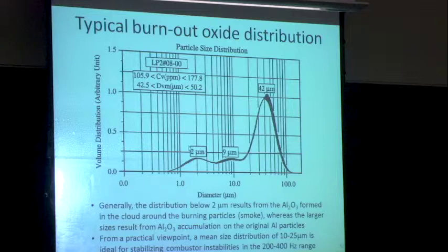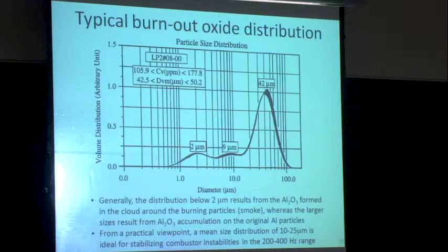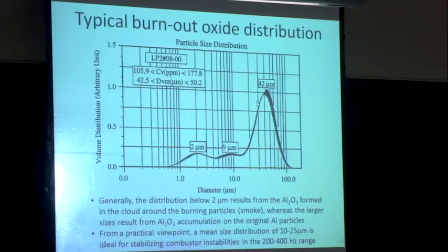The other thing, just to end this up, that's very important because of two-phase flow characteristics, drag in the motor nozzle and the flow system that is going to change the thrust characteristics, is what's the size distribution of the final products being formed. It's also important with regards to instability characteristics in the motor. And typically you'll find at least a bimodal distribution. The large particle size of the oxide being formed, as I said, is related to the primary aluminum particle, and the smaller 2-micron size is related to the particles that are formed in a reaction zone that are first at the nanometer scale and then aggregate up to basically a few microns in size. And knowing this distribution, as I said, is very important in terms of predicting performance of motors.